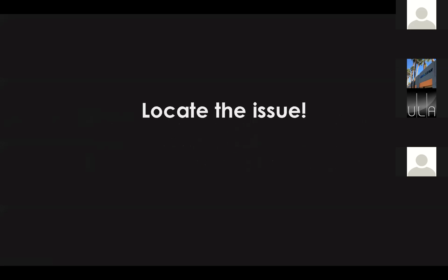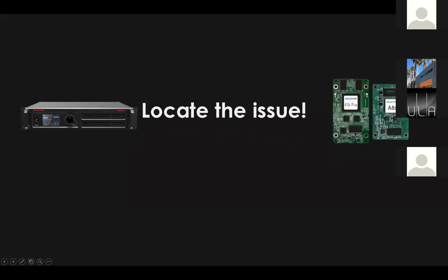I think for the first question, the most important part is that we should find out where the problem comes from. The positioning problem is the key to solving the issue. The problem is happening either on the controller side, including video source, controller, HDMI cable, or on the receiving card side, including Ethernet cable, screen power, modules, and receiving cards. And the screen control function will help you locate the problem.